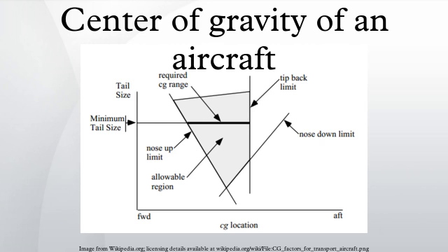Reference datum. The reference datum is a reference plane that allows accurate and uniform measurements to any point on the aircraft. The location of the reference datum is established by the manufacturer and is defined in the aircraft flight manual. The horizontal reference datum is an imaginary vertical plane or point, arbitrarily fixed somewhere along the longitudinal axis of the aircraft, from which all horizontal distances are measured for weight and balance purposes.